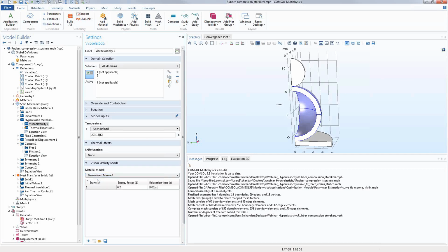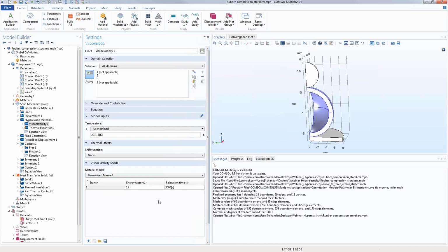If you're using the generalized Maxwell model, then it is the most accurate one, and usually you represent the material with a series of springs and dashpots. So what you need are the shear modulus of those springs and the viscosity of the dashpots. And again, to get those, you need to do a curve fitting of your real world material, which would be in the form of either Young's modulus versus time or shear modulus versus time. When you do the curve fitting, you can get the unknown parameters of the Prony series that is usually required to feed into this kind of material model.